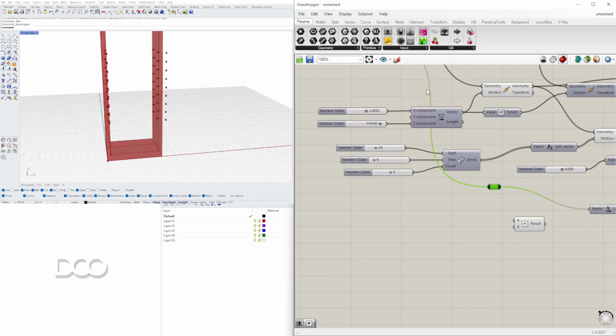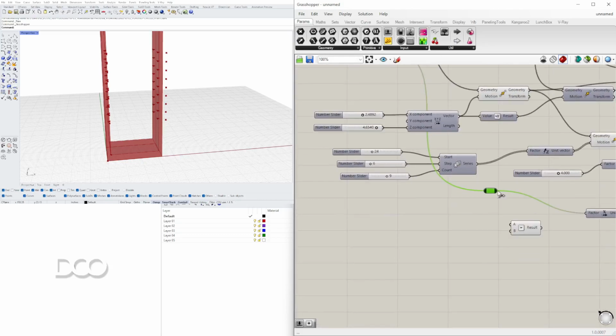And to save time and not go all the way up there, I'll double click on the wire creating a relay, bring that into the minus. Now we can plug into the B the side thickness. Now I know the side thickness is the smaller one out of these two because this takes care of the sides and this takes care of the heights.